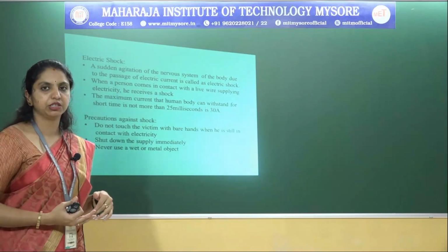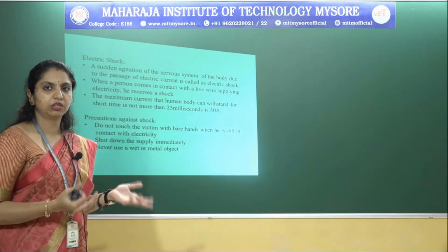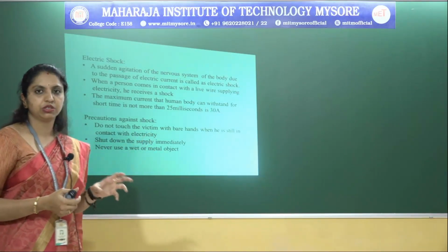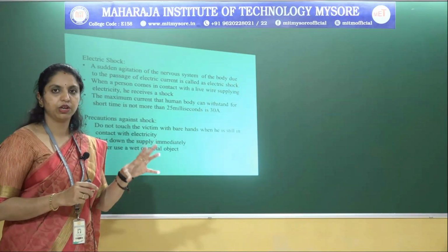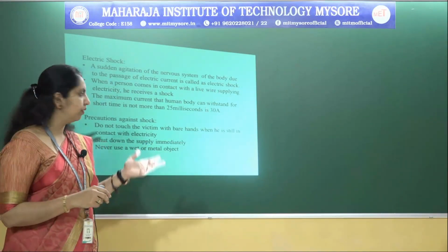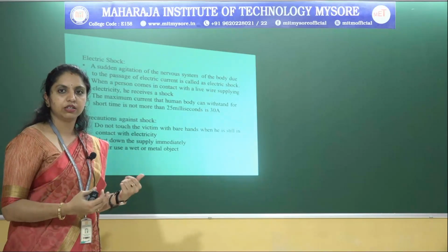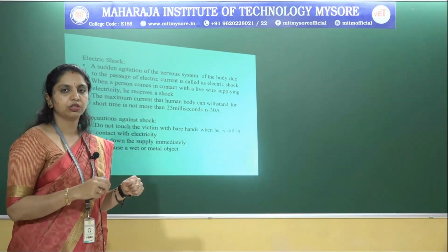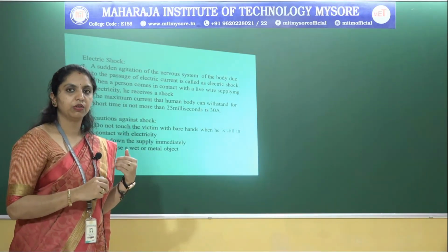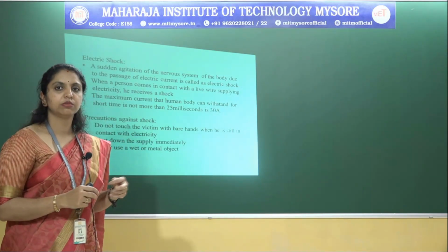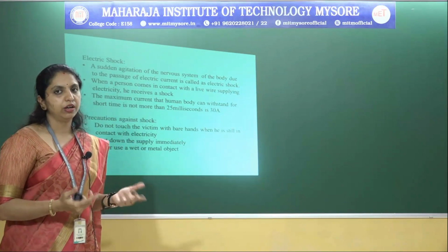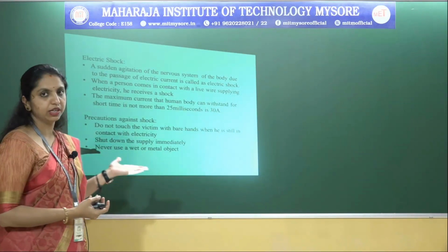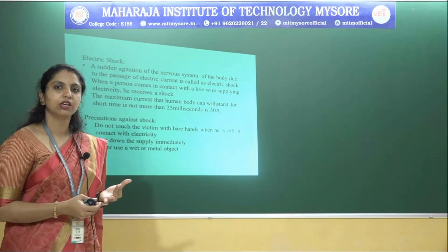Similarly, we have preventions of shock. Already you are aware of these preventions. We should not touch the switches or the distribution board with wet hands or with any metal object. And whenever we want to operate the internal part of the switches or repair the wiring system, the supply should be off, and we should wear shoes or sandals.